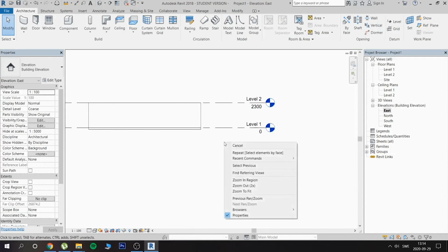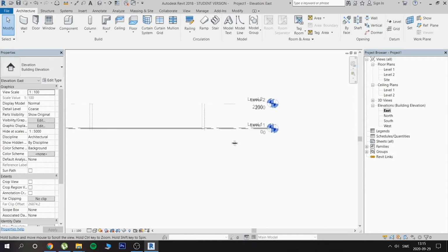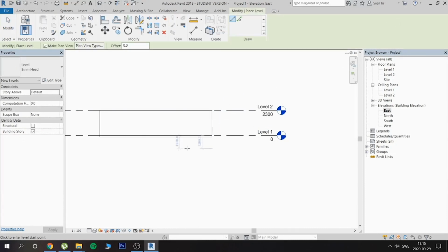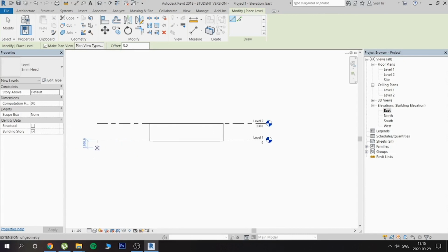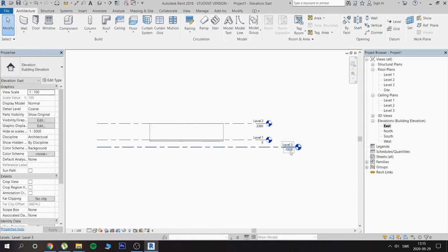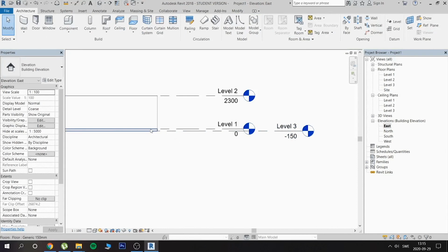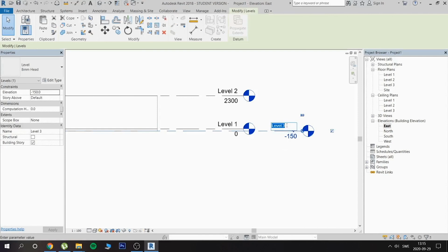And you use the same kind of way to put down the floor inside the building, but you put them inside of the walls instead of on the outer side of the walls. So this is actually something that you should do in the beginning of every project. You put down the different levels that your house is built upon. And this is just because it's simpler to connect the different building materials to the different levels.